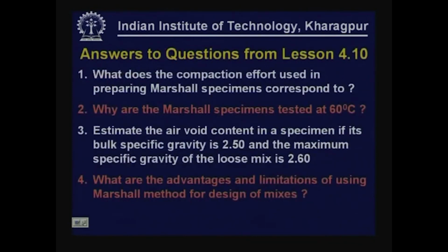Let us take up the answers to the questions that we asked in the previous lesson, that was lesson 4.10. What does the compaction effort used in preparing Marshall specimens correspond to? Normally we prepare Marshall specimens subject to 75 blows on each face, especially for heavily trafficked volumes. The compaction effort corresponds to the density that is attained after several years of traffic.